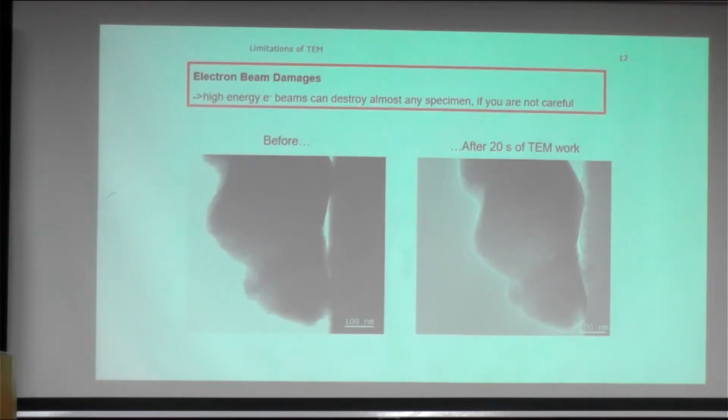You also should think about this, and if you know this issue, you can maybe play with your settings in TEM. You have different settings. You can adjust beam energy, you can adjust beam dose, and you can maybe use special methods like low dose imaging for very highly sensitive materials.